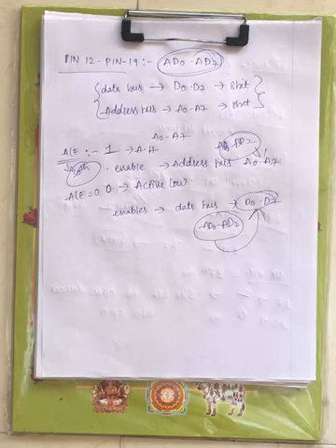Now this is how ALE and AD0 to AD7 are interrelated. When it is 1, A0 to A7 bits are carried over AD0 to AD7. When it is 0, D0 to D7 bits are carried over AD0 to AD7 lines. Now this is about your ALE, address latch enable signal.